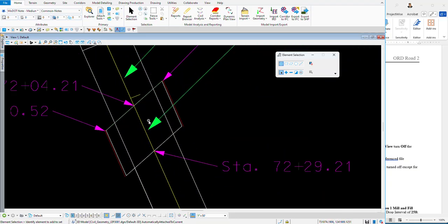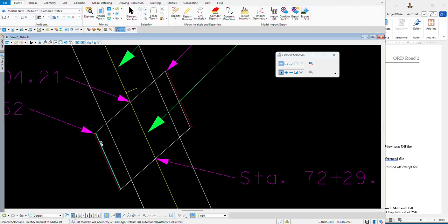The other thing to talk about in here is we're going to build the bridge indent off of this line and this line and this line. We're going to do it counterclockwise. We're going to come in here and build an alignment around here with no radius. It's a complex element around it. We're also going to use these red lines out here on each side, and you can see when I hover over them, there are traffic control barriers.